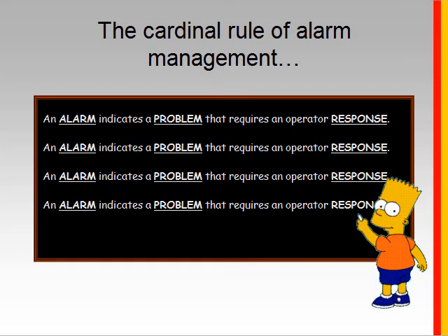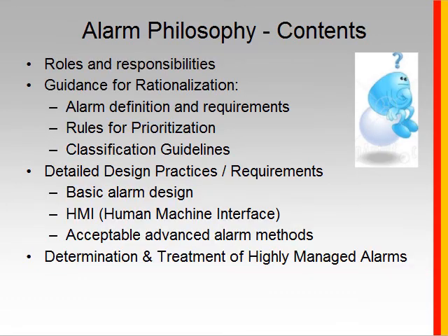In fact, adhering to this principle and always thinking about what would happen if this alarm is not responded to, or does this alarm really indicate a problem that the operator must respond to, and have we defined what the response is? Is there something they can do? This really dictates or will address many of the most common alarm management issues. So just sticking to this core philosophy or core tenet of alarm management will eliminate many of the most common alarm management problems.